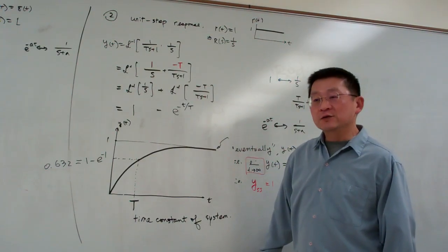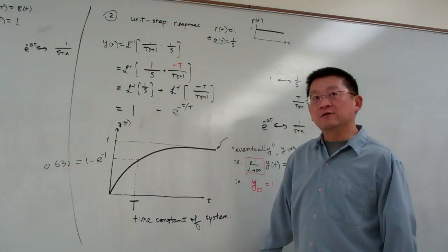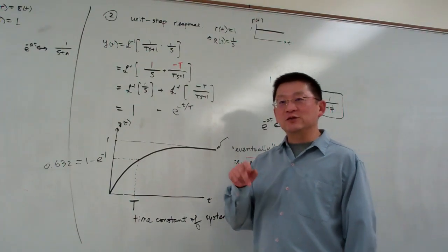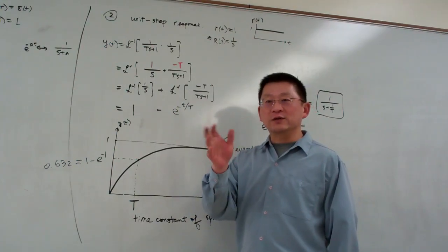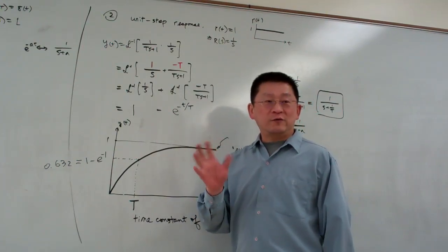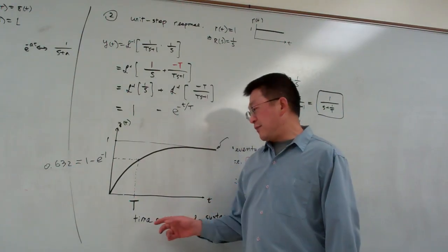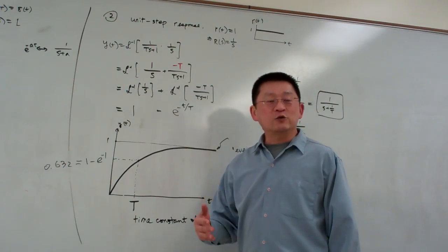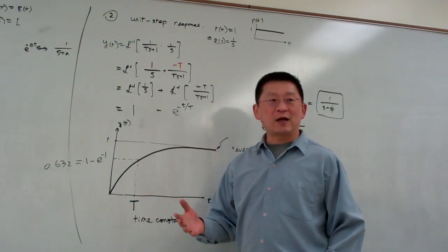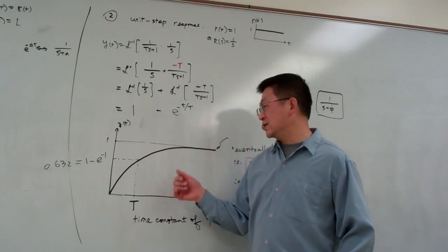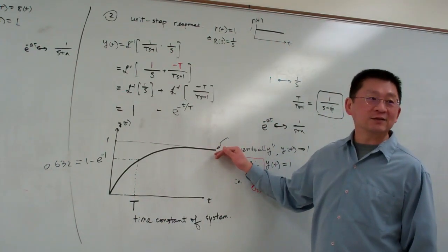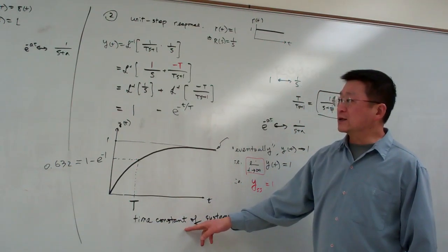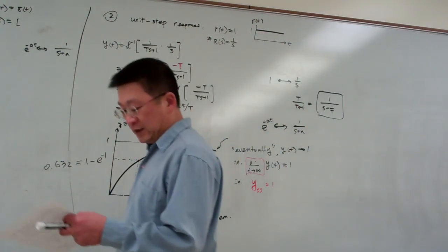Then using the wave function, if you're going to use the function generators to see something, you must come up with an appropriate function design with appropriate frequency, and that frequency must match the time constant. Otherwise, you won't see anything. Either the function could be too fast, so the system cannot catch up, or the function is too slow, so the system basically responds as a constant. So this is the very important physical meaning here.